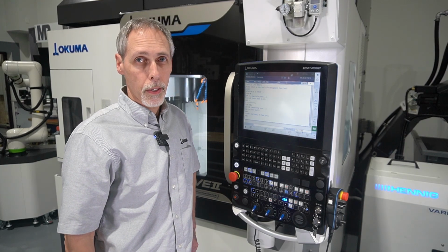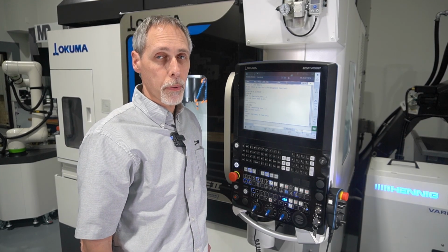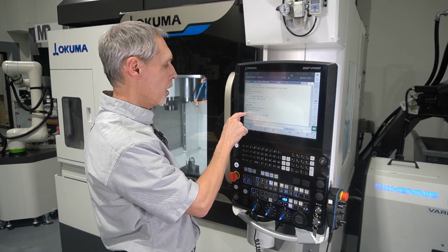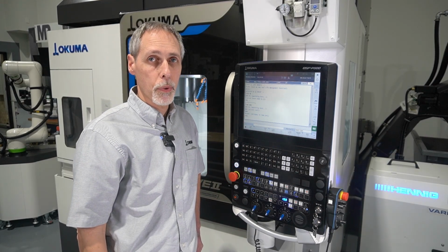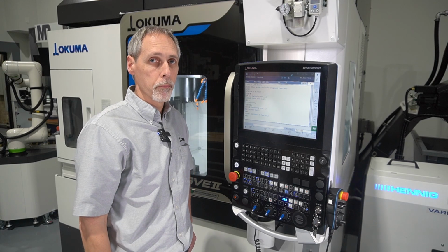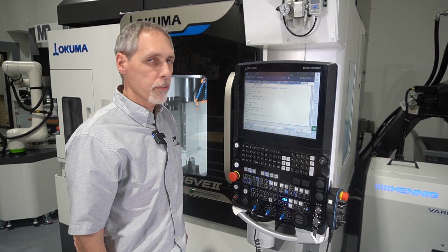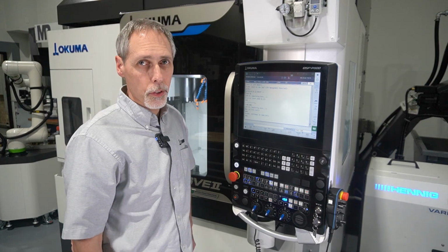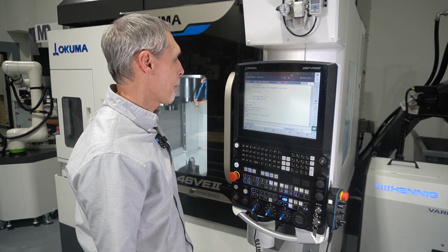You could actually do that in MDI. It's going to stay on until you power the machine off, or it will turn off when I give it a TLFOFF command in the part program, which I have at the bottom. So the tool life off command is optional. I typically don't put that in the part program.